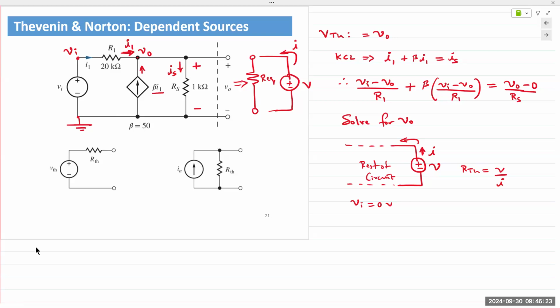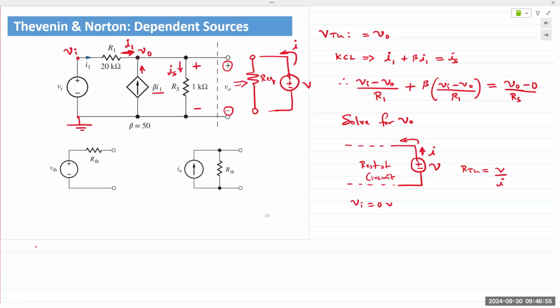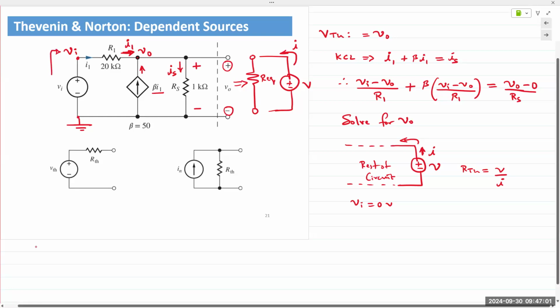Yes. It is important. At the beginning, so the question being asked is about the polarity for when we make the assumption about Thevenin voltage. Well, you can make an assumption, right? So here we are given the polarity, so we don't assume anything. But if nothing is given, we assume the polarity. And we base those assumptions on certain logic. Meaning if the power supply is connected to the plus here, we know current is coming this way, right?